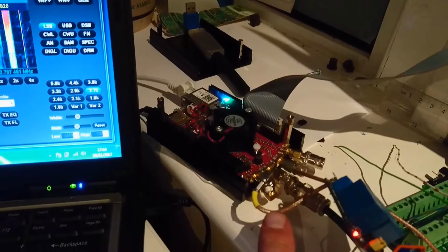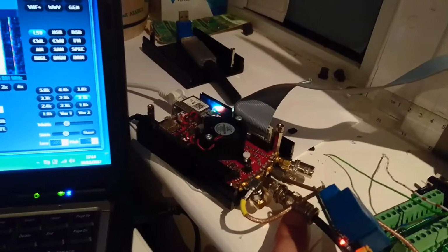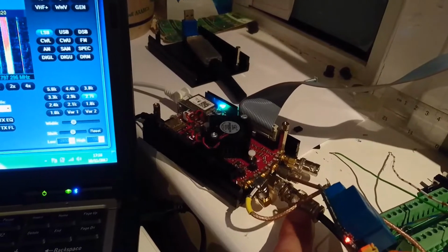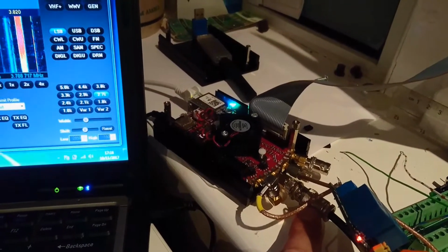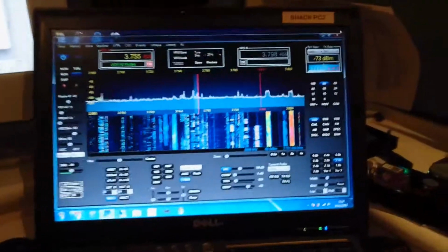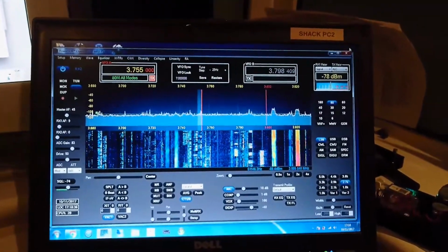This is on the inverted L, and this is using a Faraday loop tuned with a little homemade transformer and some varicaps, which is at the bottom of the garden. So it's about 20 foot in diameter. So at the moment this is 80 meters.